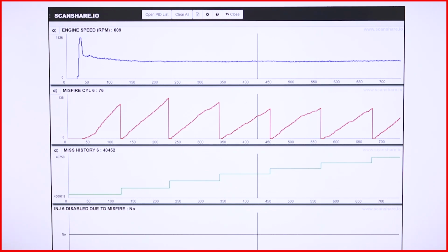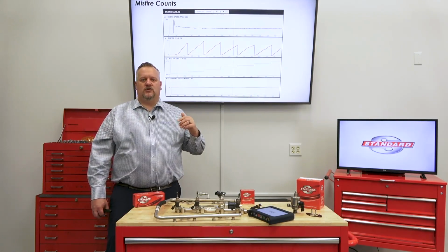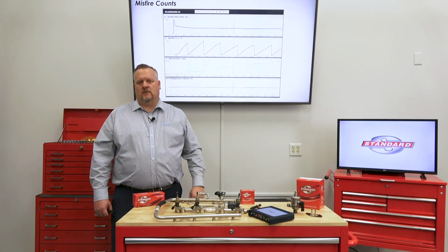Now, it's hard to show all the data here while keeping this a relatively short story. I don't want to show the rest of it, but it was noted that the misfire seemed to be lessened when the technician was driving it down the road. So this is predominantly an idle-related concern.